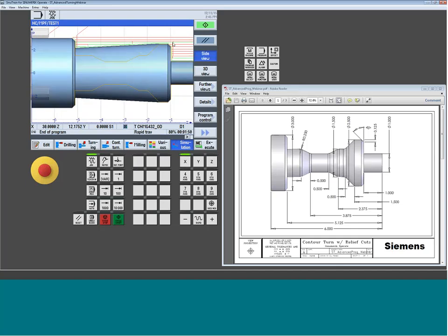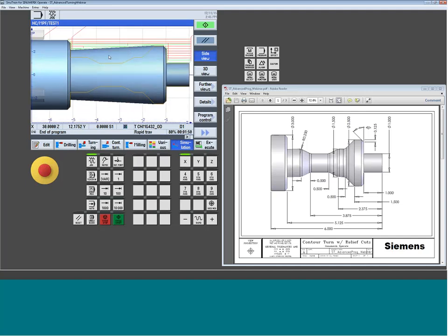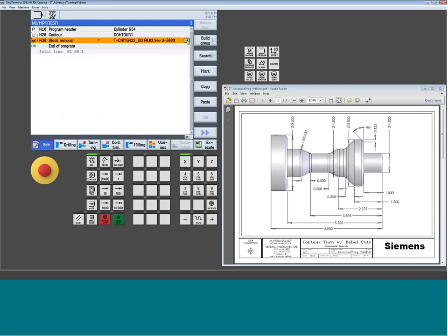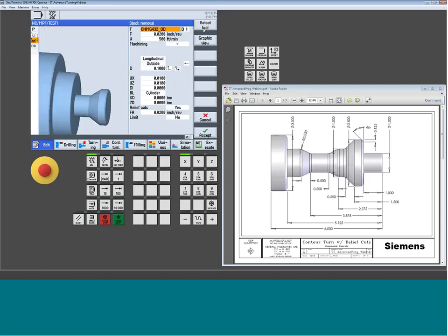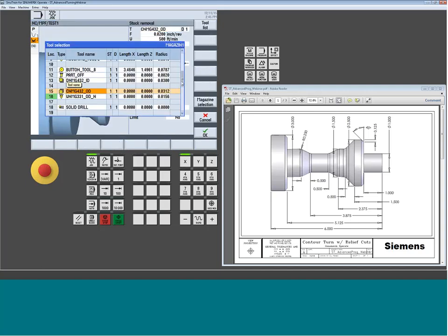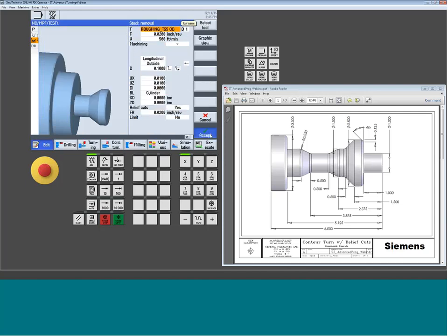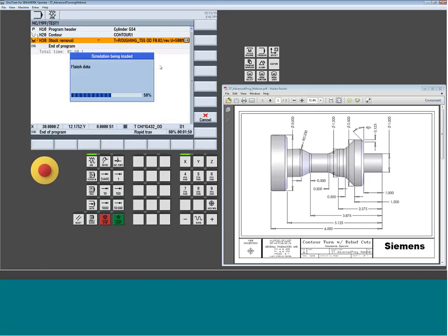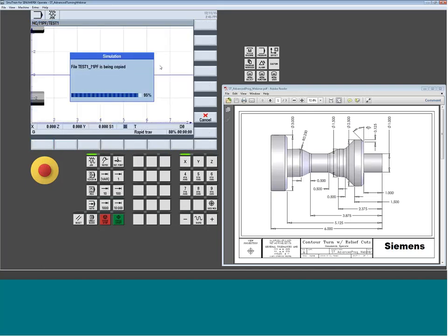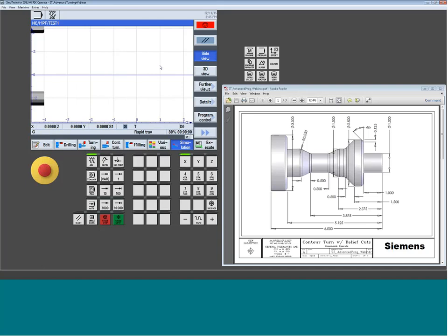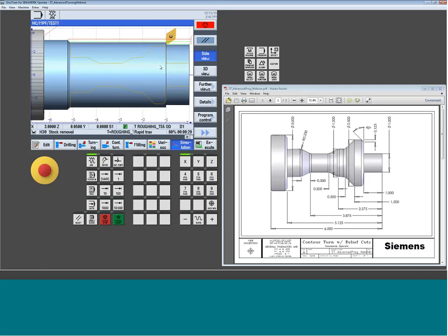All right, so I'm coming down. That's obviously not enough to handle machining this part. Certainly I could change tools and do a lot of residual material, or most of the time I'll choose the appropriate roughing geometry based on this first op. So maybe instead of using that tool, I wanted to pick a 55-degree tool I had in my library. Immediately with this new 55-degree tool and this oriented angle of that insert, I can start to see how much that tool will get me.